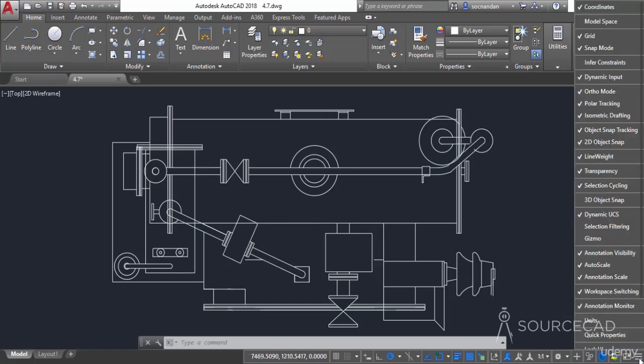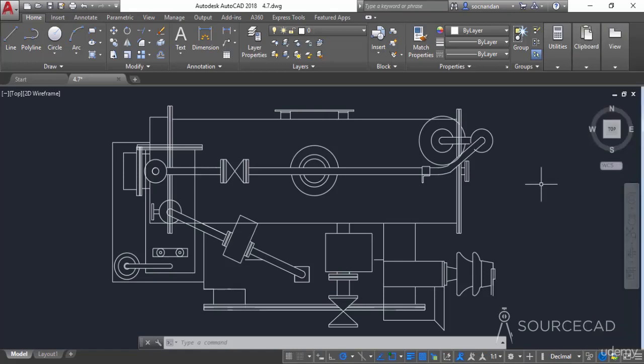Now let's look at the next option, which is units. So once again, I'll go to the customization and I'll activate this units status bar option, and I'll also turn off this coordinates. Now when you turn on this units option, you'll see this unit status bar which shows the current display unit, which is decimal in this case. So right now all the dimensions will be shown in decimal units. So that simply means whatever the geometry you make, it will be shown as decimals. So I'll check some of the properties of these objects.